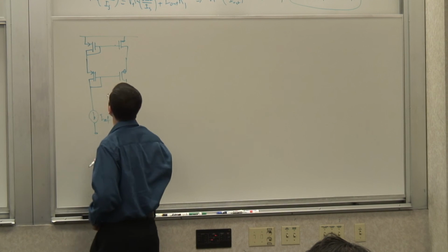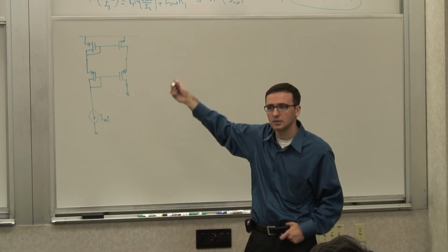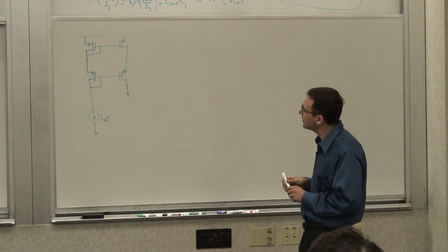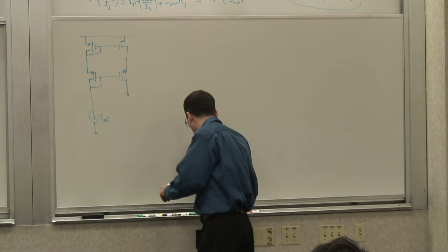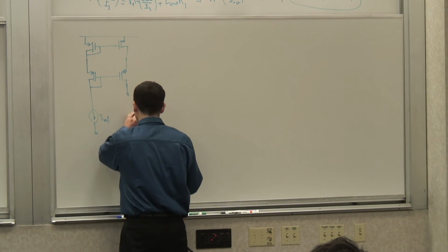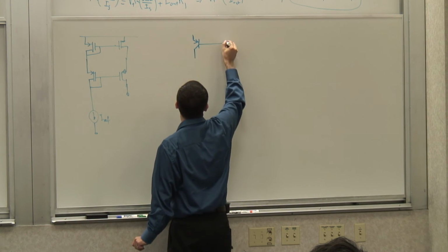And this would be the output. It makes sense, right? And you can play the same tricks here as you play there. Now, that's a current source you can make. Now, the other interesting thing about this Cascode current source, or the MOSFET version of that, is that you could do this with the PNP. So let me just show the PNP version.